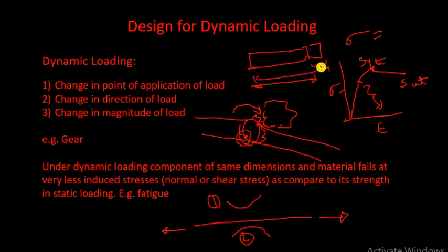There is no need for actual fracture or crushing or the exact failure which we can see by our eyes. Even though there is only a plastic deformation at stresses greater than SYT, we will still call that the machine component has failed. It is not performing as per its required performance values or limits. That is all about the design under static loading.